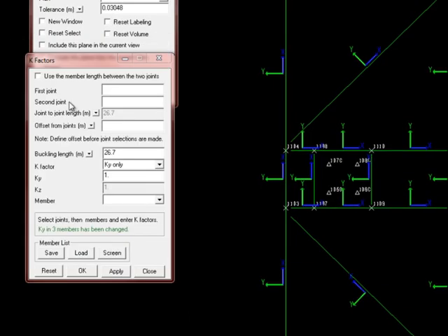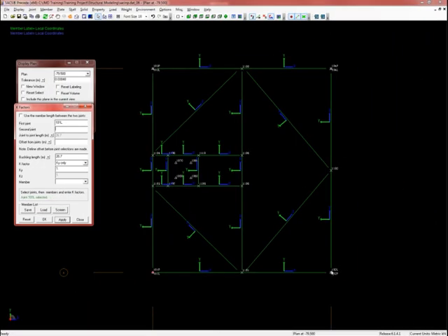We're going to do the same thing. Keep that K box open. We'll do the bottom here from this end to this end. Highlight the members. Hold down the control key, hit apply. Do the same thing for the top, 2 end joints. Click all the members, right click apply. Again, click on these joints and hold the control key down, click all members and apply. We're then finished with that elevation.